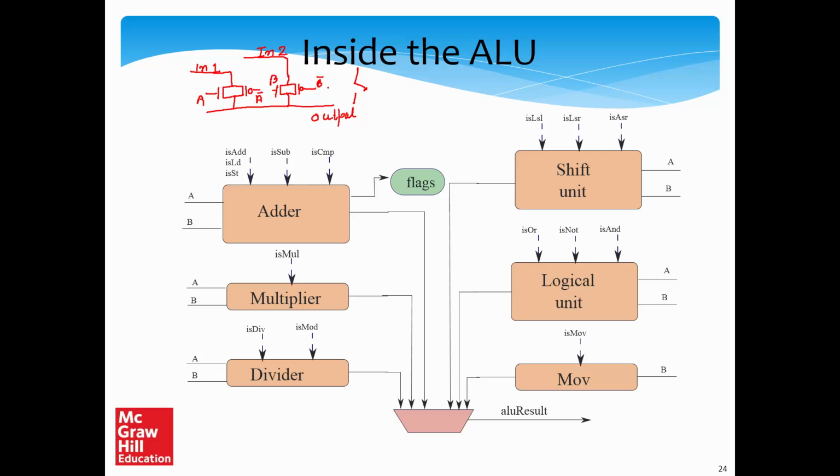Similarly, we can connect ten other inputs to the output wire, and as long as we ensure that one of the transmission gates, which is essentially just a single pair of NMOS and PMOS transistors, is enabled, meaning conducting, the output will be equal to that input, and the rest of the inputs will be floating.